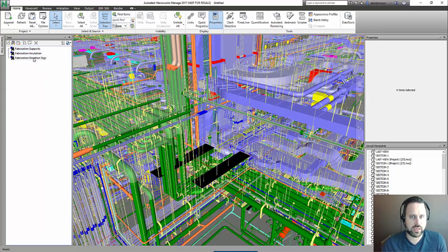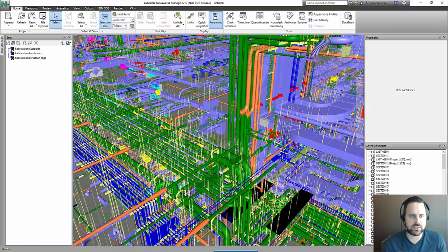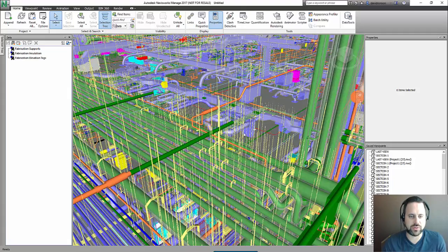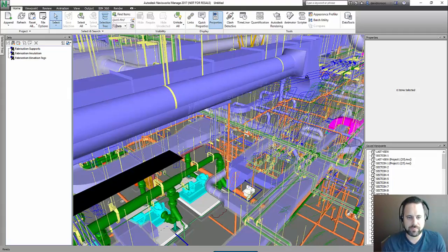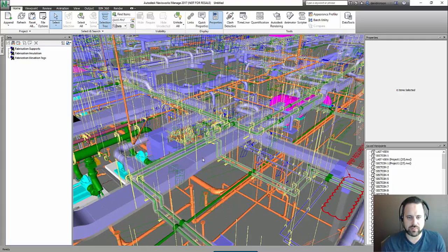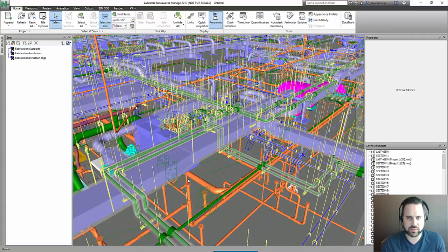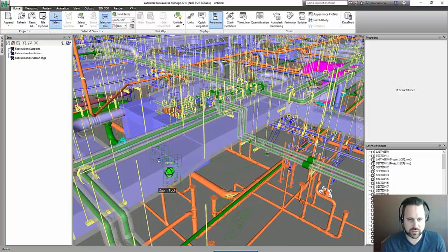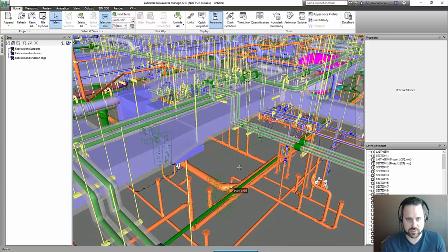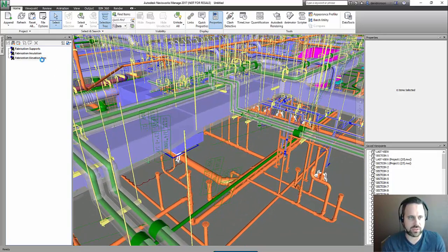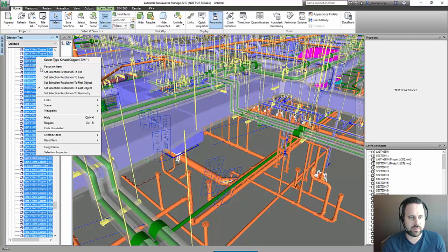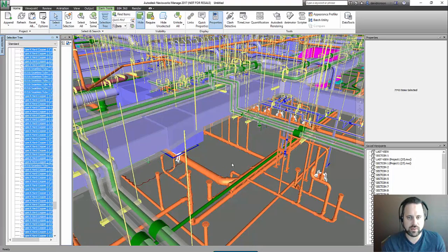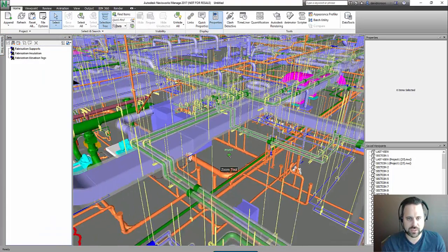All right. And elevation tags. Because tags are attached to the actual fitting itself, they show up in the model in random places, and they're really annoying when you're doing coordination. You'll see them here. They're kind of light, so difficult to see, but let's go ahead and turn those off. I've created a search selection for that. Again, I'm just going to right click in the selection tree and hit hide, and they're gone, just like that.